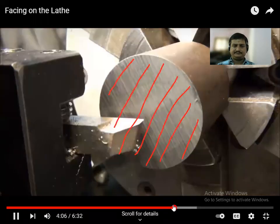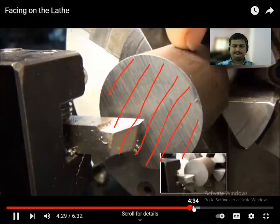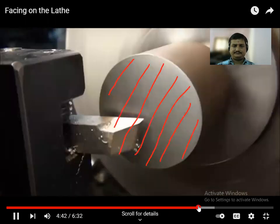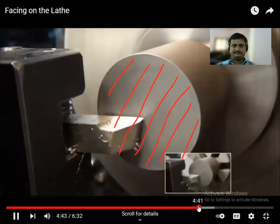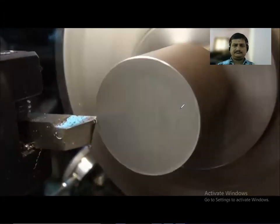Use the same old 4 times the cutting speed. Remember, that only applies to the outside. I like to bump it up a little bit. Cutting, I like to start with enough RPM as we get close to the center of the stock. Okay, for roughing out, for rough cutting, I like to start on the outside and feed in.